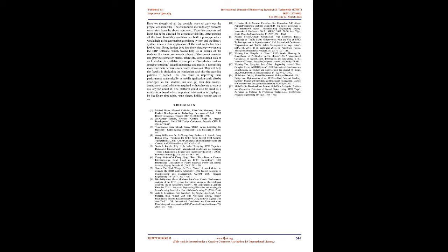So in the model proposed we make use of the RFID system to help in checking out from a library. The flowchart gives the explanation of the system, where the student enters the library, his RFID tag is scanned and marks his incoming to the library. After collecting his books he proceeds to checkout, where each book has an RFID tag which will be sensed at checkout. In our system we have kept the permissible limit as 2 books per person, and if the number of books at checkout is more than the permissible limit we hear a buzz sound and a red light is seen from one of the LEDs. If not, the data will be processed and stored in the SD card for future reference.